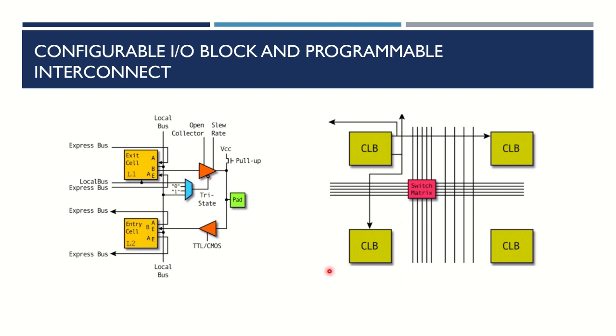The interconnect has three types of general purpose interconnects. One is single line, the second is double line interconnects, and the third is long lines. The grid of horizontal and vertical single line interconnects connects an array of switches that provide a reduced number of connections between the signal paths within each box. Direct interconnect lines provide the routing between adjacent vertical and horizontal CLBs in the same row or column.